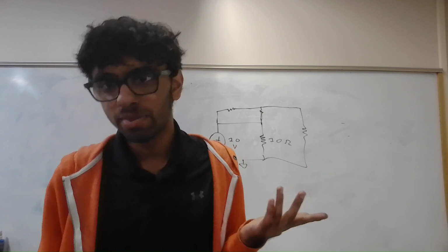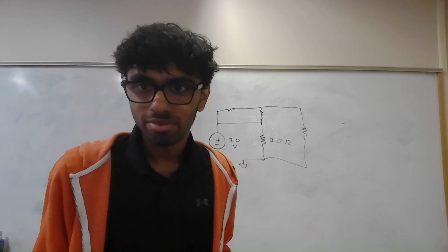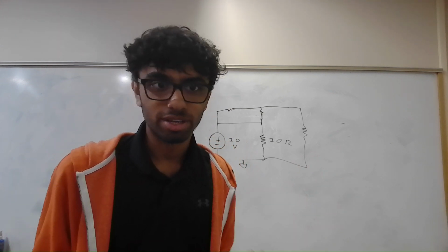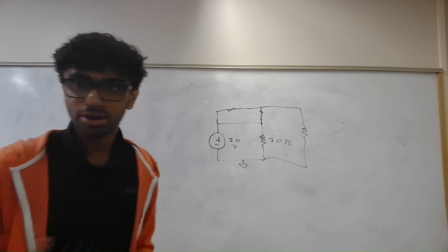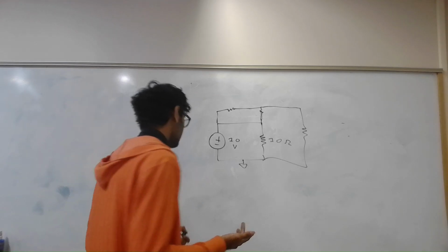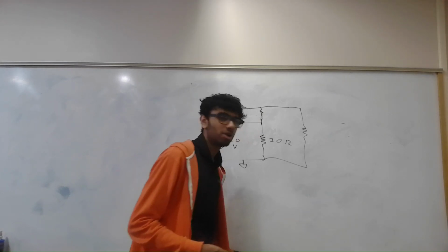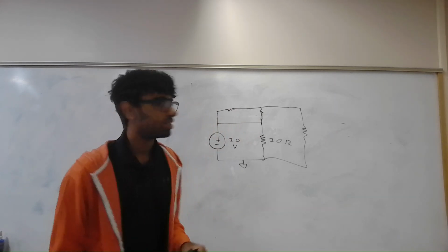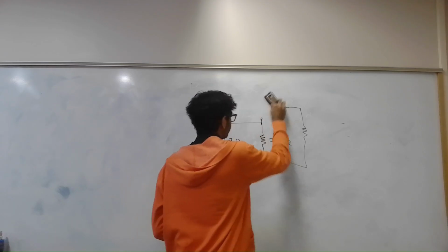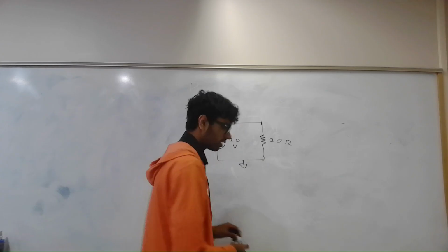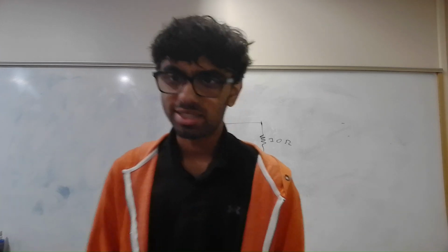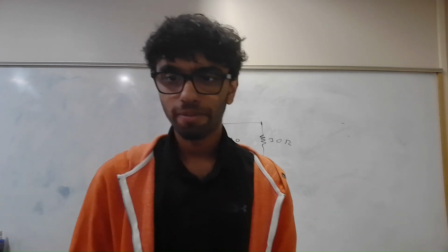So simulate it, see how much power it supplies, how much power each resistor dissipates. And then the third question, which you can do on paper, or you can just simulate, is kind of thinking about what leads to a lot of resistance and what leads to a little resistance. So there's basically 2 different ways I can attach resistors, in series and in parallel.